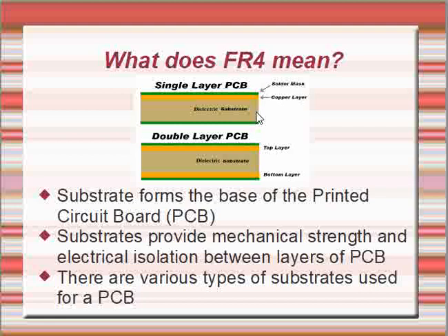So when you are designing a multi-layer PCB, it is the substrate that is allowing you to divide it into layers, and hence you claim that you have designed a multi-layer PCB, right? Now, when you are using that substrate, there are various types of substrates that can be used in a PCB. Depending on what frequency you are using the PCB at, the substrate will be decided, and basically this substrate is what determines the electrical behavior of that particular PCB.